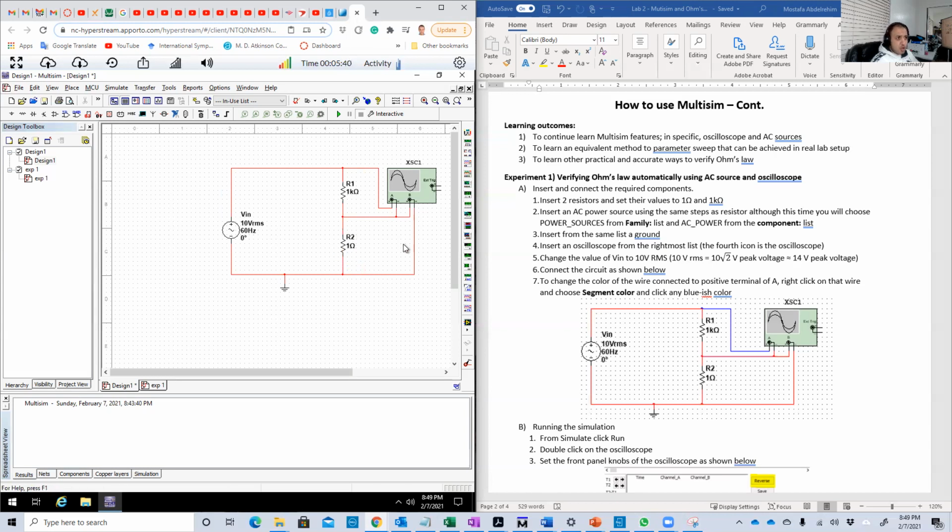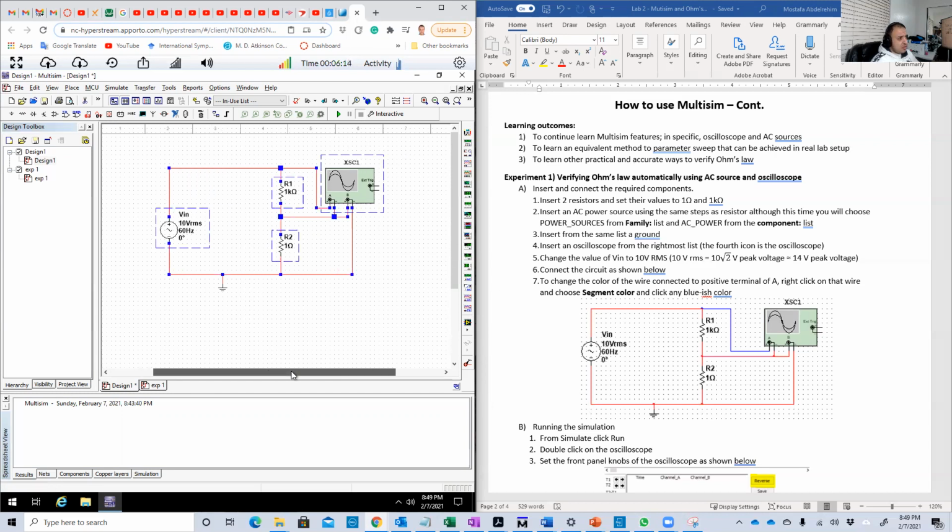So the voltage shown by channel B on the oscilloscope will also be the current of R2, and the current of R2 is exactly the current of R1. One may say no, because here is where the current goes, and at that point it should branch. No, it will not branch, because the oscilloscope is a voltmeter, and a voltmeter theoretically has infinite input resistance, so the current in those branches is zero. Okay, now we are ready. Let's move it a little bit to the center, yes.